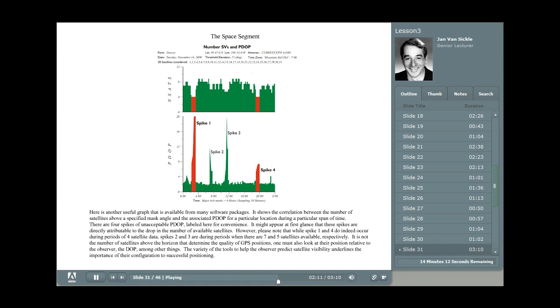Well, going past about 12 hour and moving on, the circumstances are very good. There's many satellites, the constellation is healthy above the horizon, and the PDOP is very low. But between 18 and 20 hours, we reduce down again to 4 satellites, and then again the spike in the PDOP occurs. So, as you see, it's not really as straightforward that at all times the PDOP will be low and the constellation will be good.